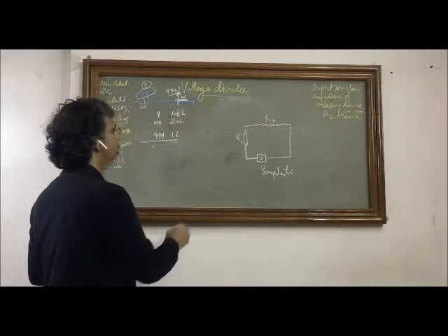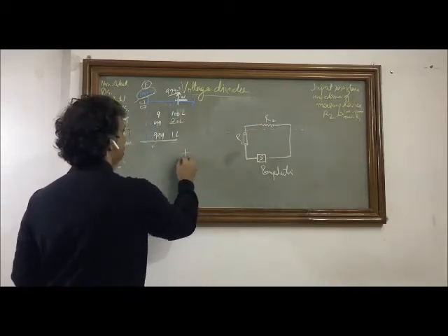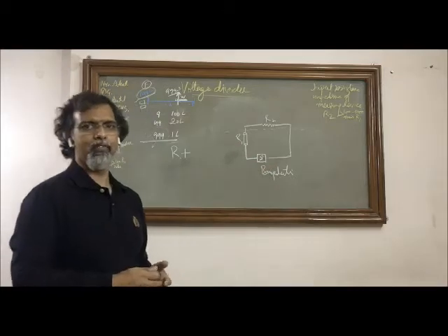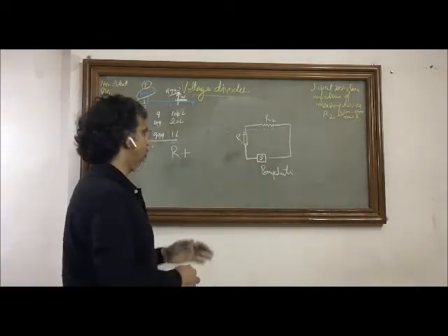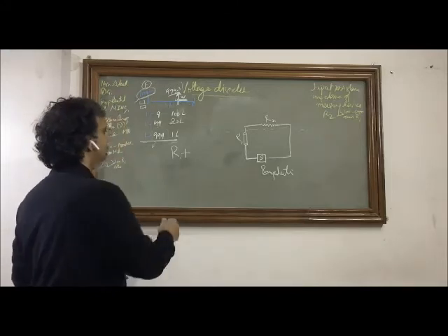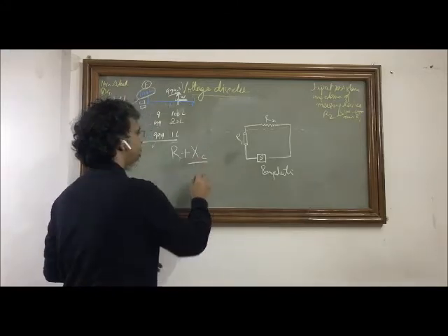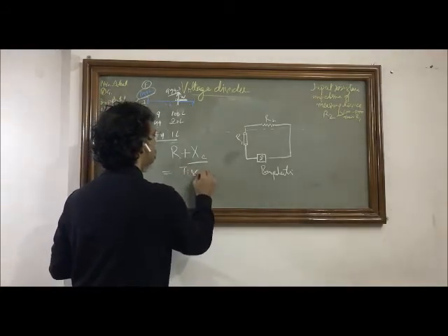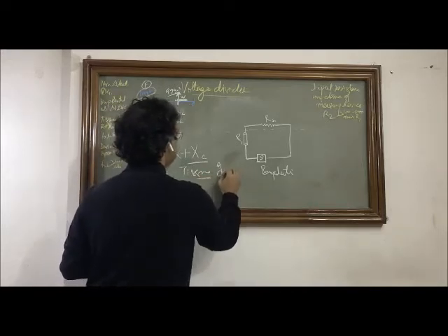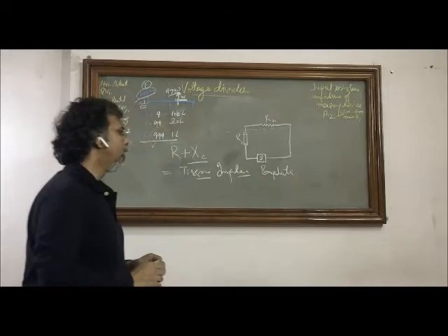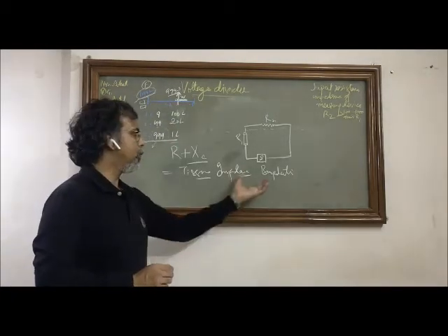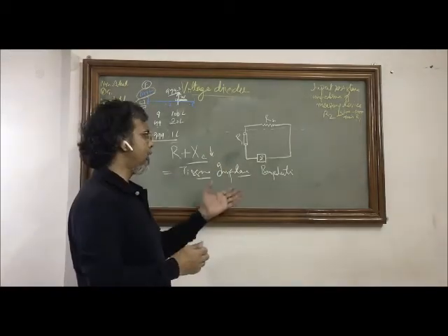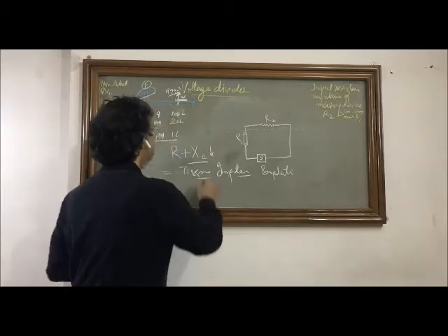And you know, the sources of skin impedance are, number one, the resistance, the ohmic part. The material through which the current is flowing will definitely have some opposition, and that is the ohmic part, which is due to the electrolytic conduction, and the other part is the capacitive reactance part. So because of these two, we have a complete tissue impedance, and the more the frequency of this biopotential, the less is going to be the capacitive reactance. So there will be a variability, because depending upon the range of the biopotential frequency, this value will vary.